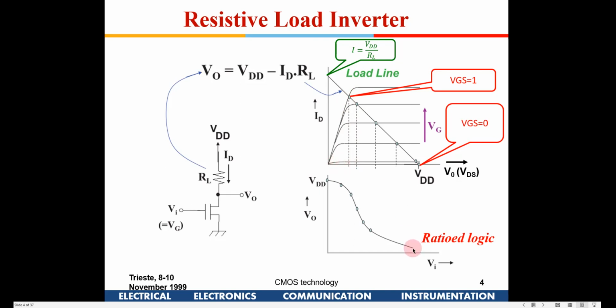So if you see, this curve is not touching the x-axis. If I have to explain it, ID is restricted here by the size of this transistor, right? So unless ID is equal to VDD divided by RL, you can't reach this point, right? So that is the reason you will have this intersection point here. Basically ID is not reaching the required levels, so that is why this doesn't reach here.